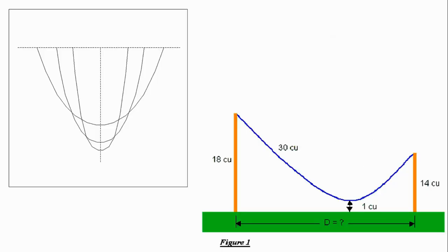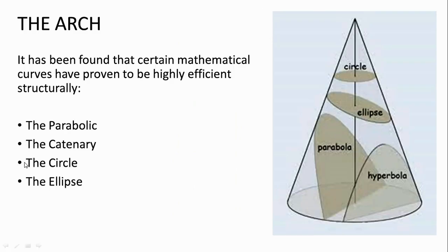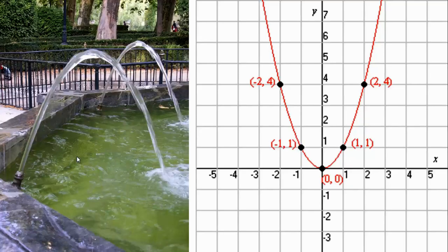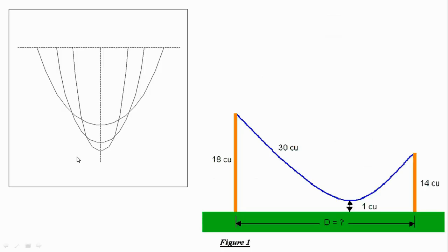This is called a catenary curve. You may have heard that expression, C-A-T-E-N-A-R-Y. Have I mentioned them? Yes, there it is, the catenary. So this is a curve that develops when you literally hang a rope or string or something that is flexible from 2 points, and they can be eccentric, as shown in the diagram on the right here. The points don't have to be at the same point. But you will develop here from this hanging process a natural curve.